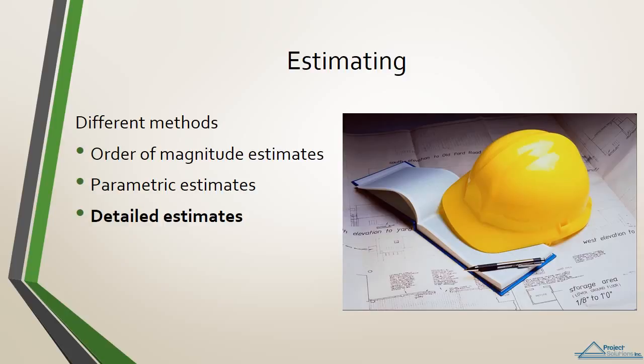There are about as many different methods of calculating an estimate as there are construction companies. The distinct types of estimates in use today can be categorized into a few basic styles. Order of magnitude estimates. Order of magnitude estimates are essentially ballpark figures. Construction firms most commonly use this type of estimate as a tool in the screening process when evaluating a project's desirability. They are very quick to produce and do not rely on detailed design information. The accuracy of an order of magnitude bid generally depends on the experience of the estimator.